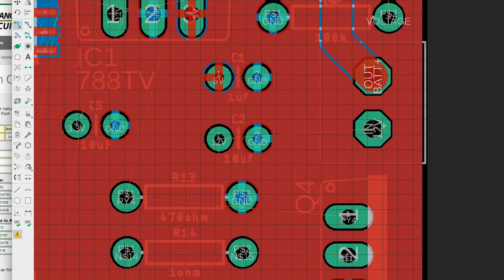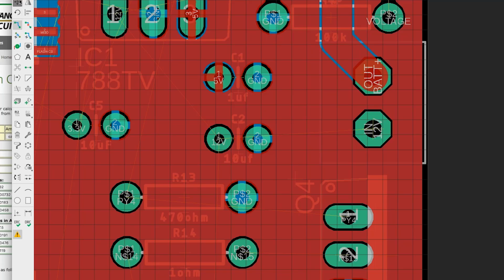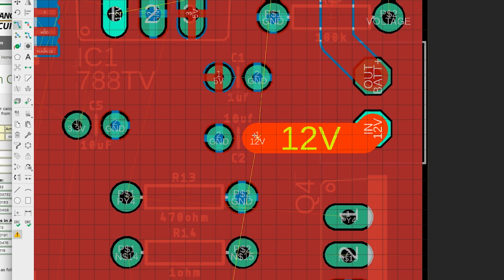We'll continue on by routing the trace that's coming out of the switch port, and we'll do that by clicking here and then routing it here. And you know what I notice here is that there's a better way to route this signal. And the way we're going to do that is if I click the move button and we turn this part. Turn it 90 degrees, 180 degrees, place it right back where it was before. And I'll click the rat's nest button again. And now we can route it a lot closer to where it's coming from. So once again, the takeaway here is that you can change your design as you go.